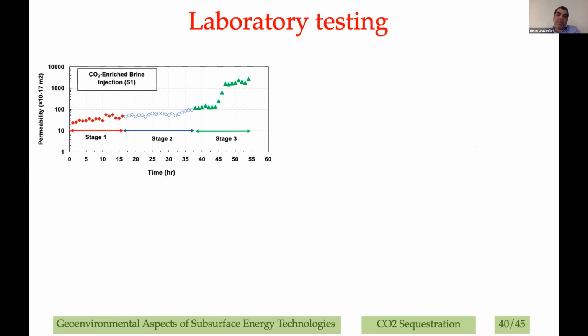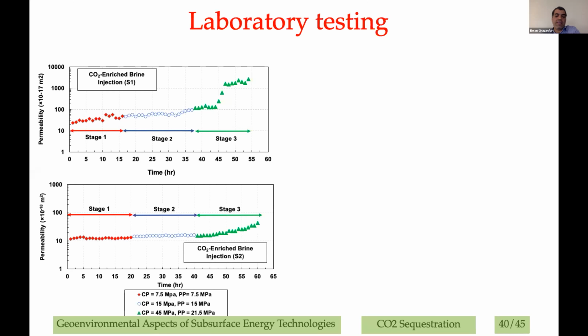Now in the lab, we have tried to study the response of CO2 injection into deep saline formations using rock specimens that resemble those formations. And what you can see here in the plots, these are basically the CO2 enriched brine injected into sandstone specimens in different stages over time. And you can see how the permeability of that sandstone specimen is increasing over time because of the injection of CO2.